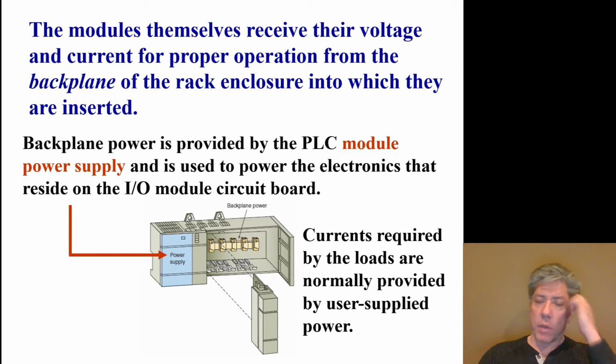Now, understand, we're not talking about field device power. Sometimes people will wire off of this power supply and also connect it to the front of the IO modules for field power. And you can do that, you just have to be very aware of power budgeting. One nice thing in the Click software is you can go into the setup, I think it's system setup as I recall, and get an idea of how much power each module is going to draw so that you can select an appropriate power supply.